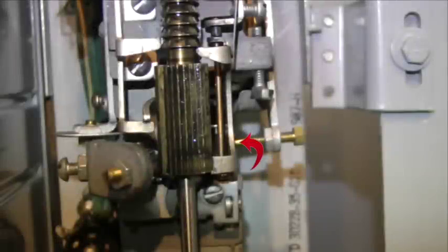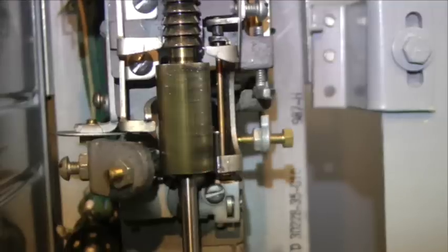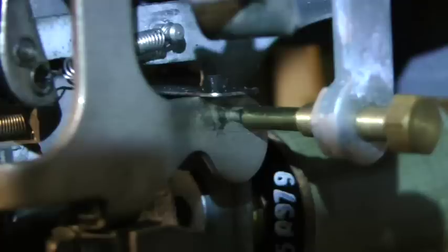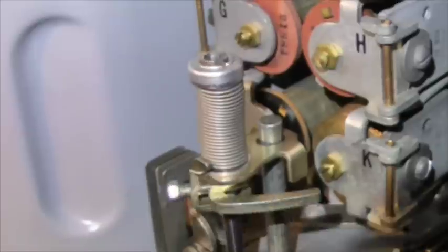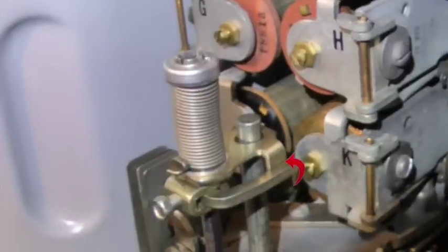The pin on the bottom of the release armature pushes against the head of the double dog, which causes the legs of the double dog to disengage from the ratchets. And it allows the release link to re-latch over the tooth of the double dog head. With the leg of the double dog released from the rotary ratchet teeth, the tension of the wound-up shaft spring causes the shaft and all of its attached apparatus to rotate anti-clockwise until it is stopped by the normal pin striking the shaft spring bracket.